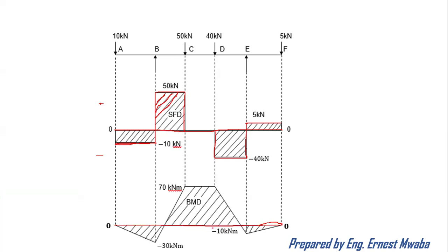So then I check my answers. What answer did I have for the bending moment at point A? It was 0. So I put a dot there. Next, what answer did I have for point B? I had negative 30. So I measure out negative 30. Remember, the scale I'm using now is for the bending moment. It may not necessarily be something similar to that, no? Because the numbers on the bending moment, the way they are behaving is different from the way these are. So here I have my negative 30, meaning from 0 going down, this is my 30. I just put a dot there.